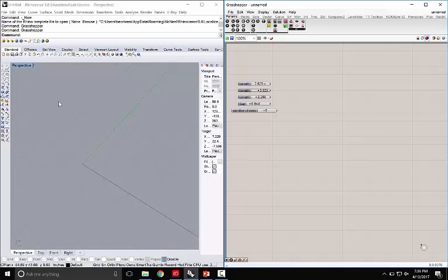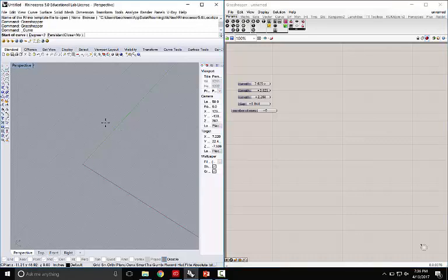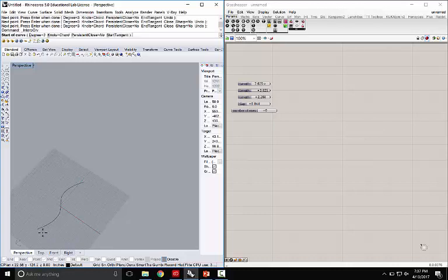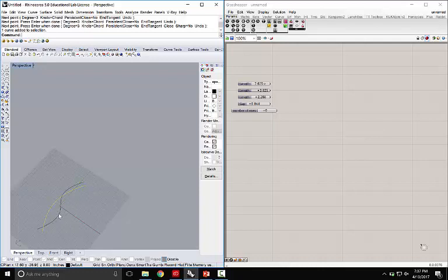So what we want to do now is define a couple of pieces of geometry. We're just going to do 2 really simple curves. So just here in Rhino, I'm going to go to the control point curve and just give myself one S-shaped curve and one C-shaped curve. At the ground, a brick wall is going to be more stable if it's S-shaped, and so I'm going to leave that as the lower curve and the C-shaped one as the upper curve. These are basically going to define a lofted surface that we'll then use to derive the actual brick shapes.